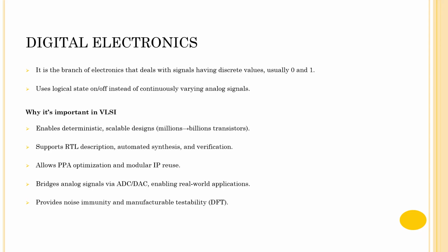Modern chips are built using RTL-based design flows described in Verilog and SystemVerilog, where logic is automatically synthesized into gates by EDA tools. This automation allows designers to focus on the behavior while tools handle the optimization for performance, power, and area. Digital design also promotes modularity and IP reuse, so blocks like ALUs, memory controllers, and UARTs can be integrated easily into larger systems.